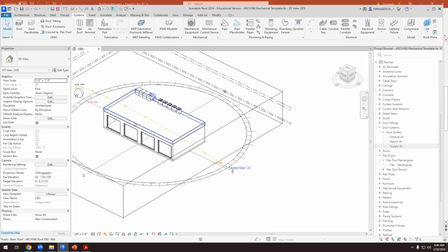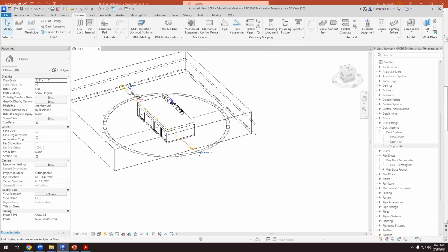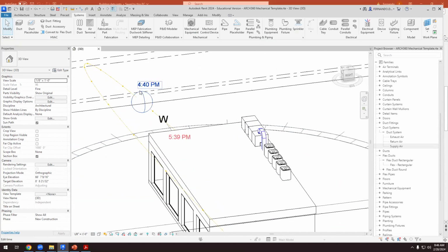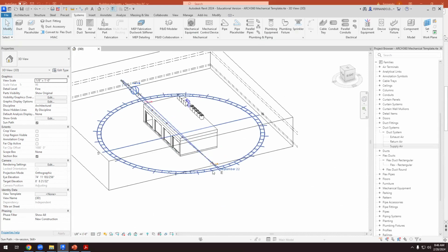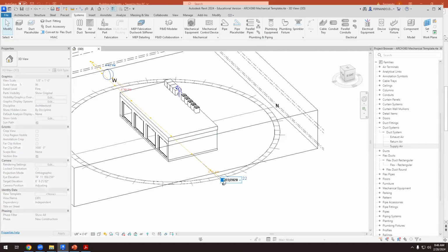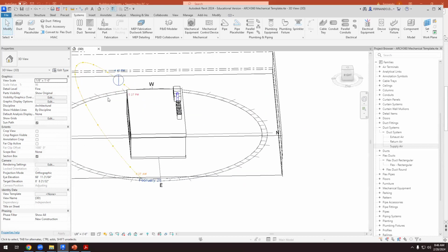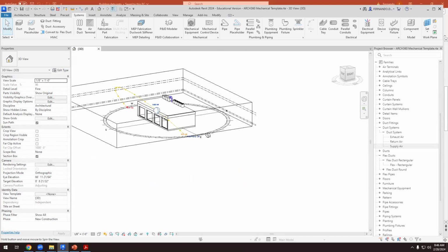So we can place the panels because we have a flat roof. A horizontal orientation is not the best in terms of solar efficiency. So we need the tilt, okay? Because the sun, as you can see, if we look at the sun path, by default, I have here September 22 and 4 p.m. I can change this to today, February 28. The year doesn't matter. So this is February 28th, and this is 9 a.m.